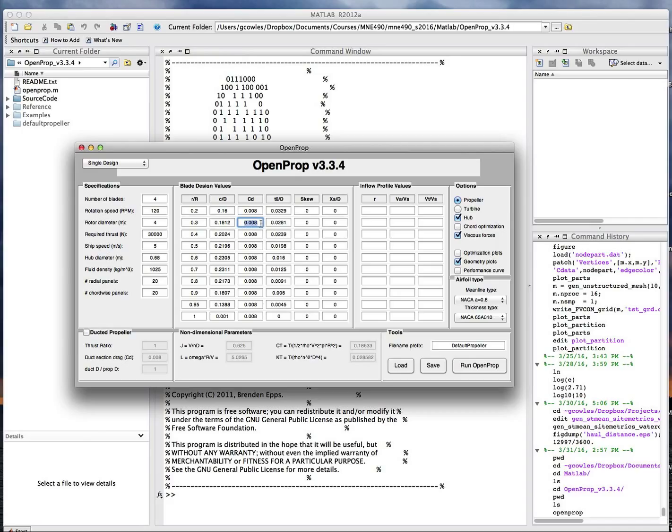Normally what you might do is take the section characteristics, which are selected over here, and get a sense of the blade Reynolds number, or maybe an average blade Reynolds number, perhaps one based on the velocity experienced by the blade section about 70% from the hub, to get a Reynolds number, to get a drag coefficient. Alternatively, you can compute an individual Reynolds number for each of these blades. Basically, as you get further away, the Reynolds number is going to increase, and come up with some cross-flow approximations. We're going to stick with these constant drag coefficients here.